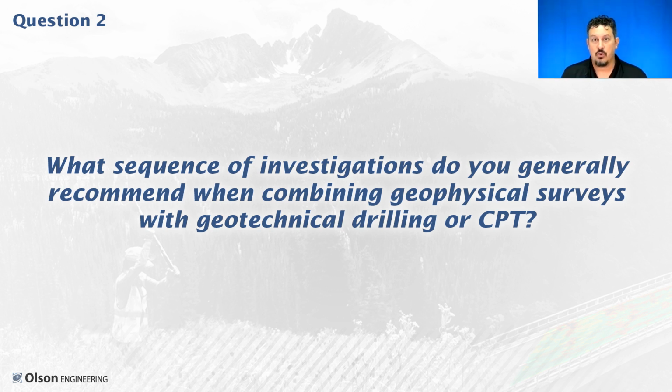If they open up some more questions, maybe do an additional survey in an area where one or more of the pushes may have put some questions around our geophysical results. And so again, my ideal approach now is I would go out and do a mobile time domain EM survey to cover as much area as possible and indicate the areas of interest.